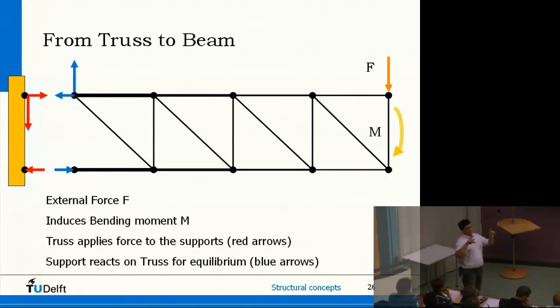As soon as there's no force and no moment equilibrium, the beam will move or rotate. So first, if I look at equilibrium in vertical direction, I do have a force here, so I need a counteracting force somewhere also in vertical direction. And here it is. This force plus that force means that the whole product cannot move in this direction.